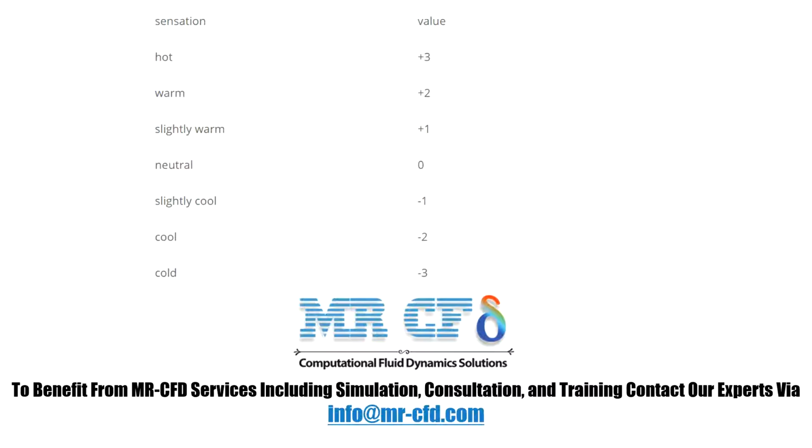and the response of their average thermal sensation was examined. As a result, the predicted mean vote, or PMV, for thermal measurement was obtained in the form of the ASHRAE thermal scale. The values for this criterion vary between -3 and +3, and according to this table, the different states of heat sensation range from very cold to very hot.